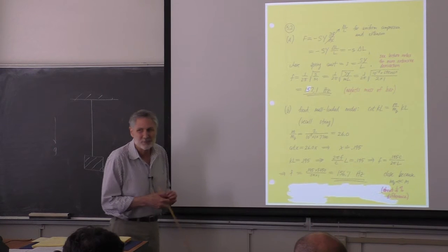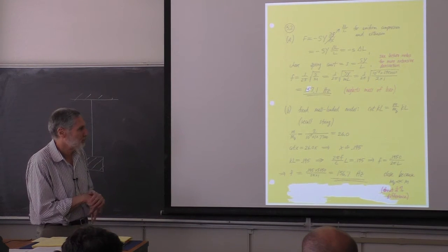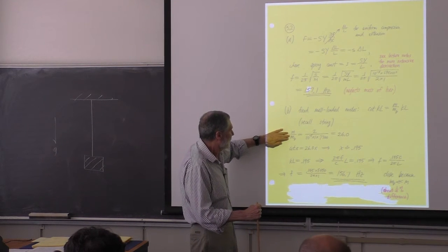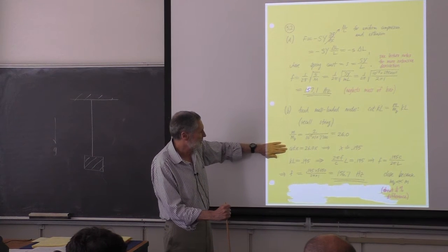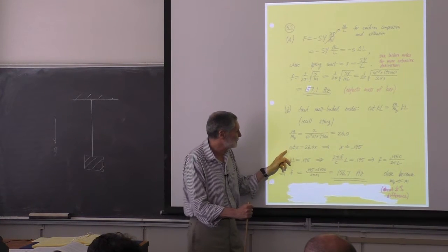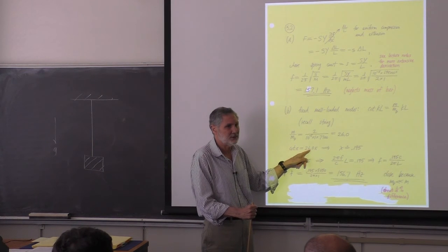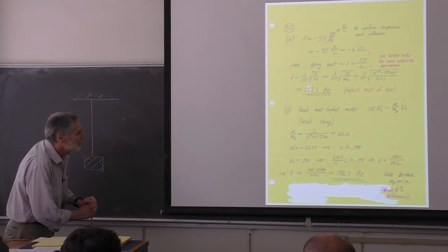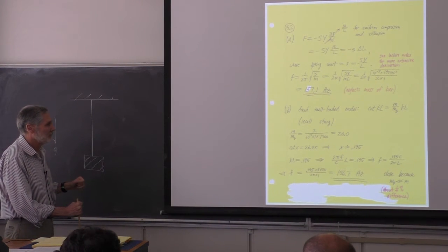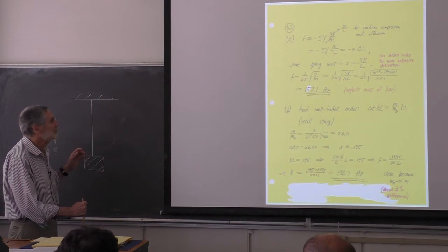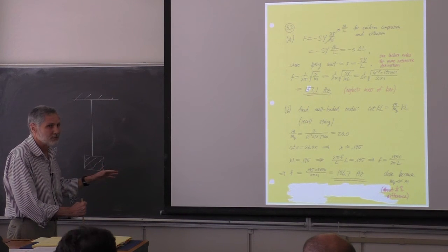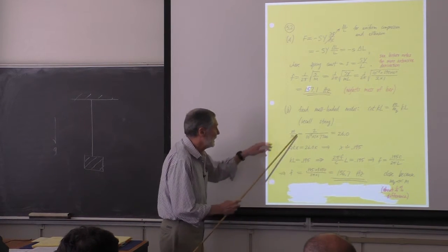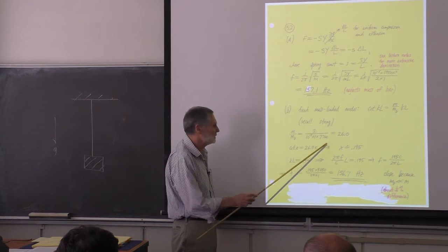What do we mean by large compared to unity? I don't know, we're going to find out. That's really, I think, part of the point of this problem here. So we now are solving this. And you know that an approximate solution is going to be just making this infinity. In that case, we'd be looking at the fundamental mode of a fixed bar, right? The mass is very heavy on the end. But we're going to do it exactly in the context of this model and use the 26 rather than infinity.